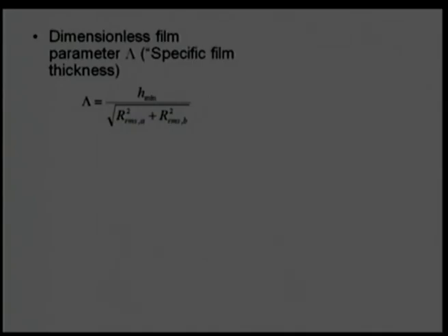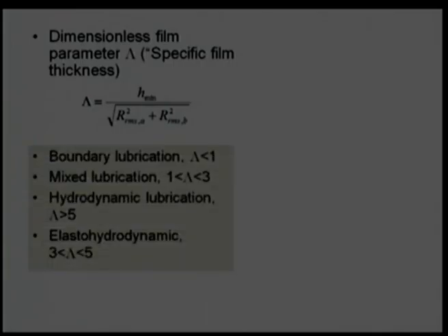If the capital lambda value is higher, then the operating mechanism will be different and the overall result may be in favor of longer life. So, we generally divide the complete lubrication mechanism into four domains. We say that the lubricant is negligible, that means there is hardly any film thickness between two surfaces.